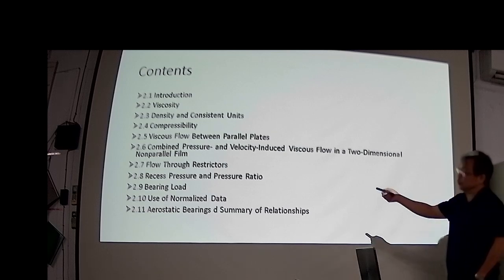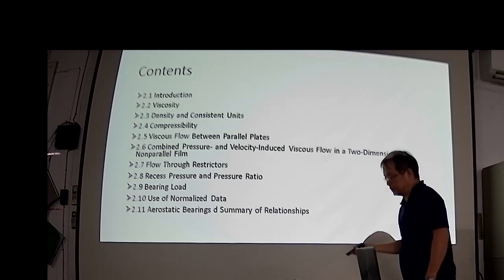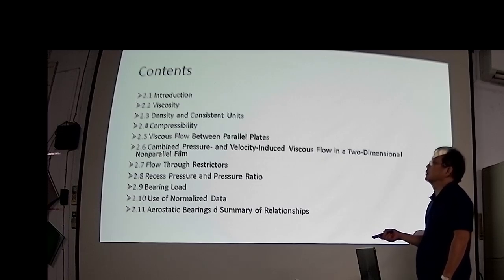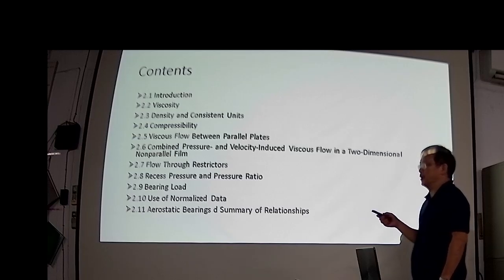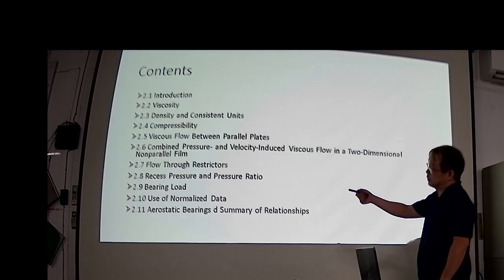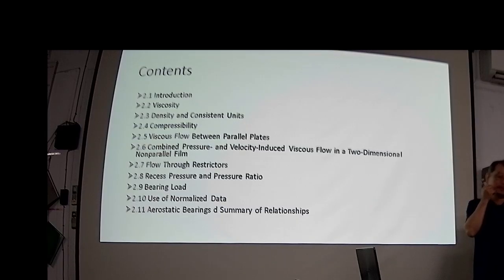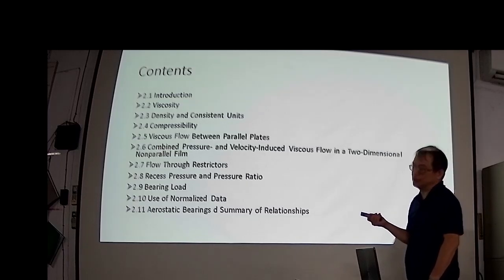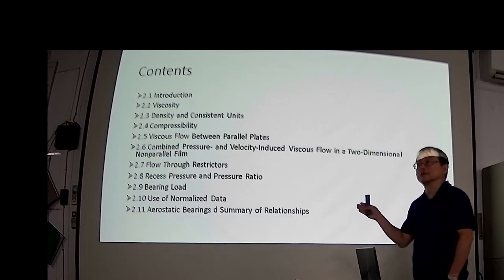So we need to distinguish the compressibility between the air bearing and the hydrostatic bearing. For air bearing, air as a lubricant is compressible when you have a supply pressure of more than 6 bar. And more importantly, you will have pneumatic hammer instability when you have a supply pressure of more than 6 bar for the transition, and